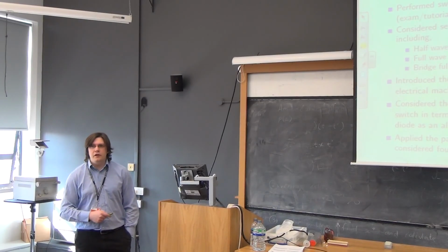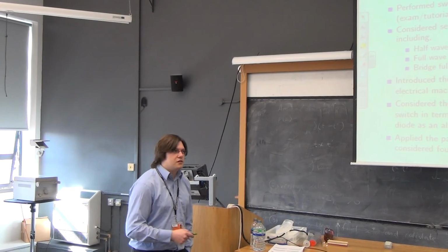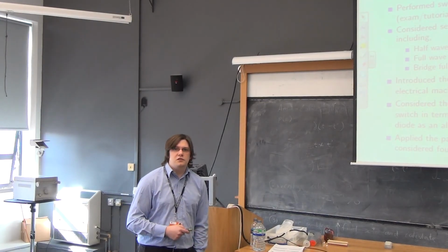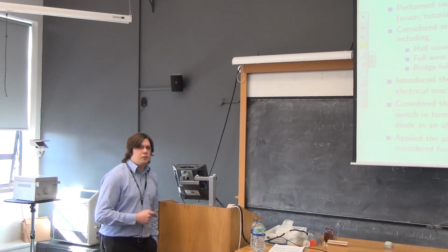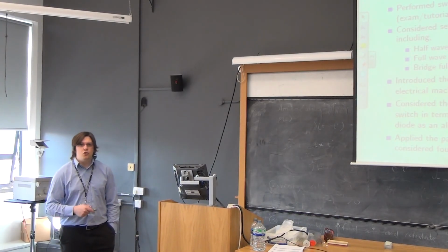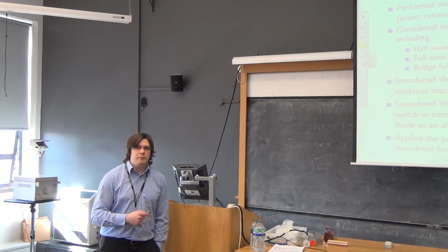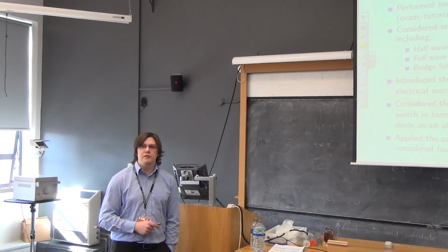And then we applied diodes to our switching circuits in such a way that the energy stored in the inductor would not upset the circuit or destroy the transistor. And then we applied that same approach that we used with diodes to an H bridge to show how the energy that's stored in a rotating machine or an inductor with a current in it can get back into the supply without damaging the driving circuitry.